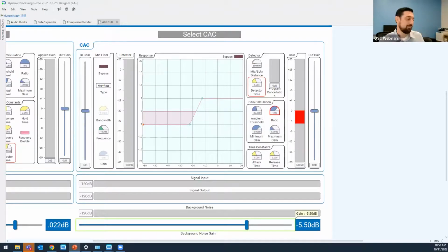Well, now the music's higher, so I feel like I've got to be a little bit louder to talk to my neighbor next to me, so I start talking louder. So now the system senses that they're talking louder, and it starts turning the music up again. And if you have that maximum gain too high, people will just climb this ladder all night. You definitely want to avoid this.